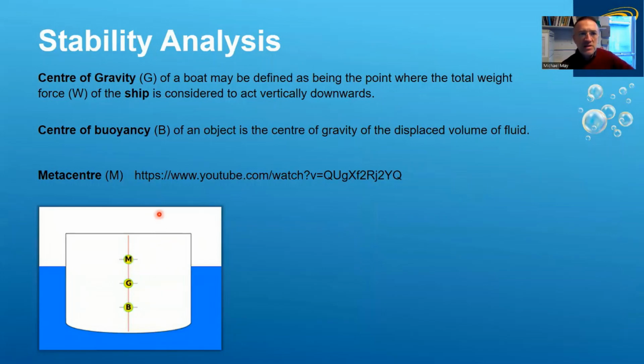So for the stability analysis, we need to know the weight of the boat and the center of gravity. In SolidWorks, they refer to that as the center of mass. We'll assume it's the same thing for the purpose of this project. The center of gravity is the center of mass with gravitational effects taken into consideration. We also need to know the center of buoyancy and the buoyancy force and the metacenter. They are all explained in this YouTube link here, but I'll explain in my own words now.